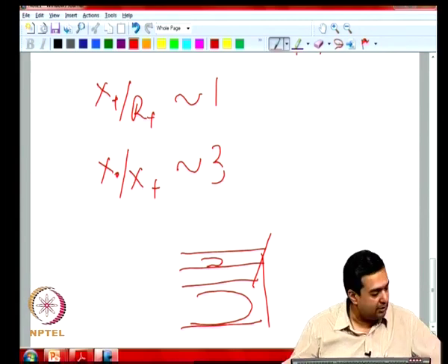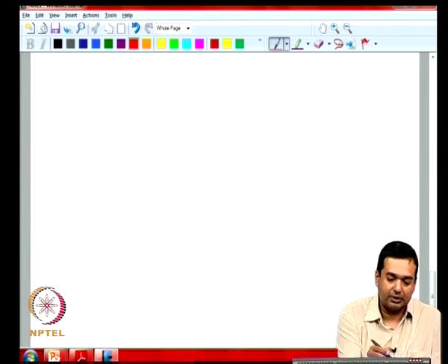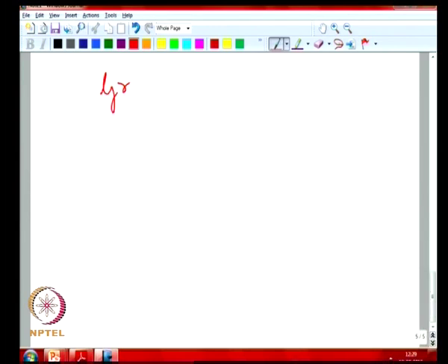If you look at a typical distribution system, there are a variety of ways of grounding. You can have solid grounding of the transformer. So, people talk about TN networks, etc. T stands for terra, where your neutral is solidly connected to ground.